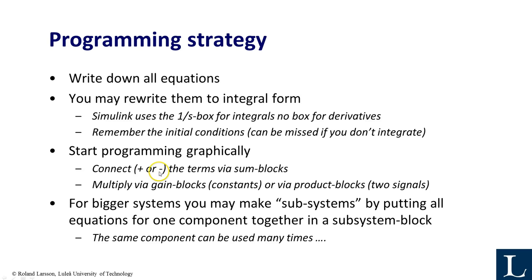You take each equation and connect them to a plus or minus block, the sum block. Use gain blocks, product blocks. There are many possibilities in Simulink, and I showed you the very simplest way of using it.